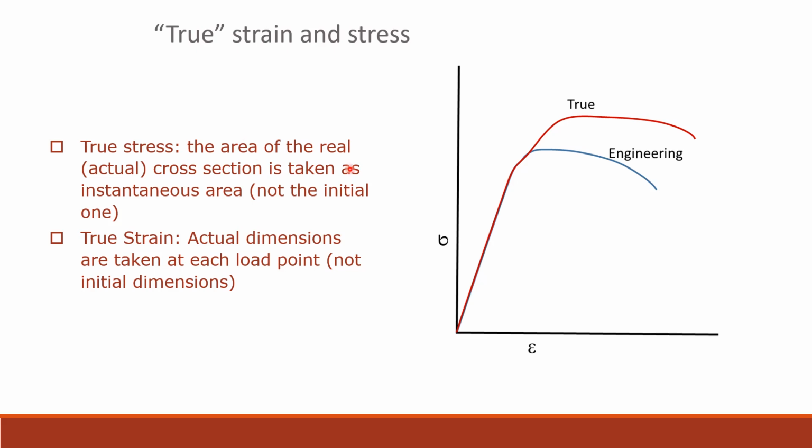To take that into account, we define the true stress, in which the area of the real cross-section is taken as the instantaneous area, not the initial one. And the same for the true strain. So we take the actual dimensions at each load point.